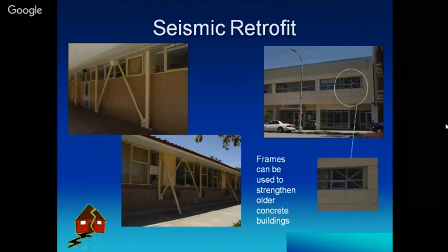As a precautionary measure we can keep, such as the things we have shown here in this figure, fluid viscous dampers. As you can see in this box, the dampers are there, and as soon as we have an earthquake, the building moves, these diagonals try to move, the liquid in the damper moves, and it mitigates and dissipates the energy of the earthquake.